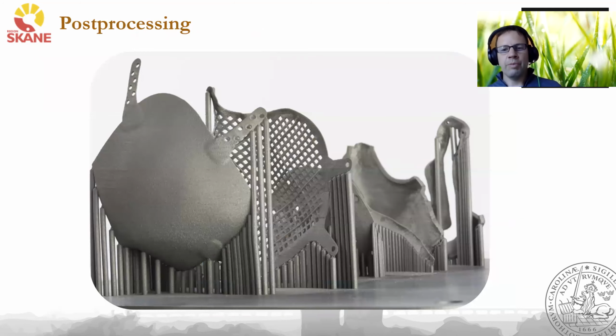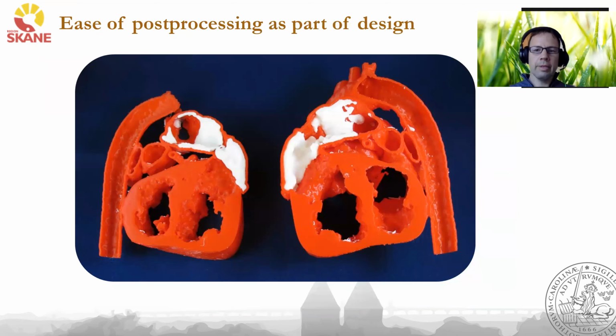So for instance, when printing in titanium, post-processing comes to a completely different level. And it's important to consider post-processing already in the design process. I will come back to this in the lecture where we'll go from images to ready print files. Often, I typically divide the print into multiple parts. That helps the doctor to see the inside details better, and also significantly helps the process of removing support structures.